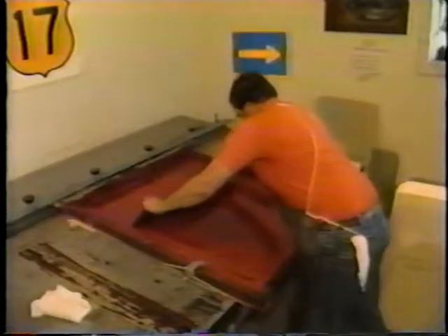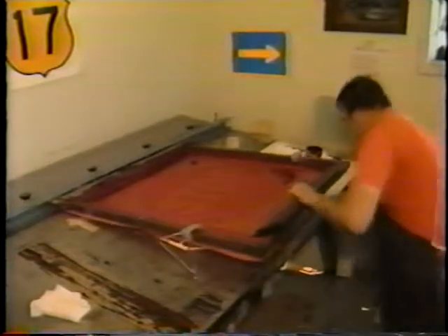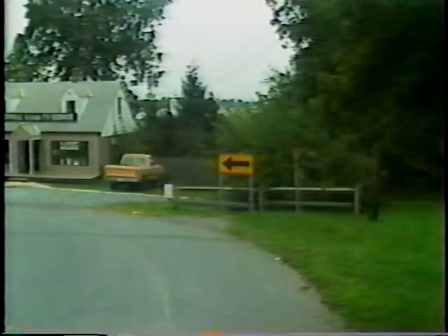Top quality traffic signs have a useful life of 7 to 10 years, but the fact is many will be left in service much longer. As a sign ages, it loses its reflectivity, so while it may appear okay in the daytime, it virtually disappears at night. Such a problem might go unnoticed by drivers who are familiar with the area.